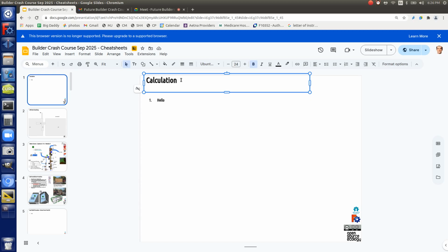If you lay them flat, you'd think, why can't I lay them flat? Well, in that direction it's much more bendable. The way you arrange wood determines how it can flex. If you laid your joists flat, you'd totally wobble up and down and you'd break them.